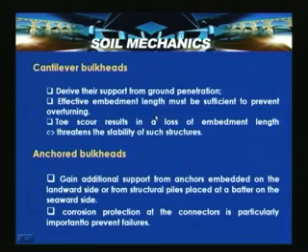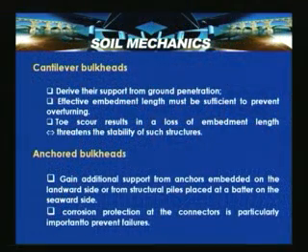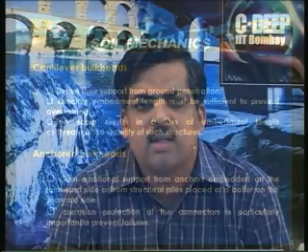If it is inadequate, overturning can occur. Toe scour results in a loss of embedment depth and threatens the stability of such structures, so any scour in front of the wall is a concern.